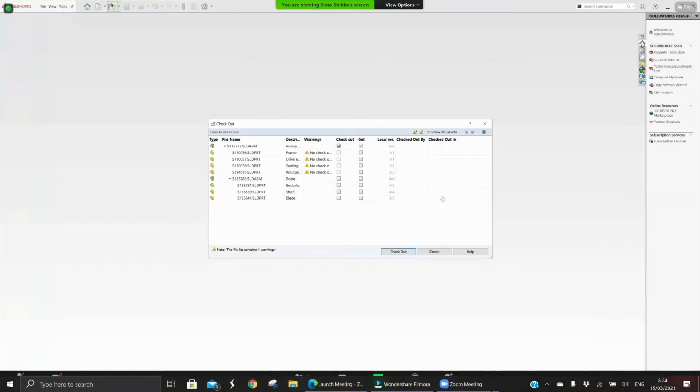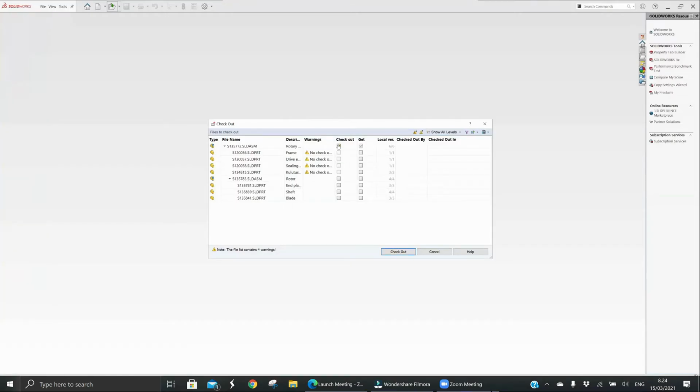So now I'm opening the file again and I'm going to do this checkout, and this is exactly what I think Kang did. So if you just want to open something to see the file so that you won't get the ownership for the file, then you should not check this box, but you could only open the file. When this checkout is selected, it means that you get ownership of a document.